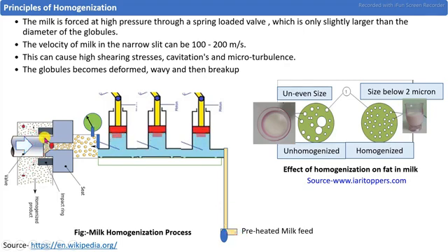In the pressure homogenizer, there is a specific wall. The gap between the walls is very small, slightly more than 2 micron, and the high pressure preheated milk is passed in between the walls. This wall is adjustable as per our requirement. We can adjust the internal pressure, and due to the high turbulence and the resulting shearing force, size reduction of the fat globules takes place.